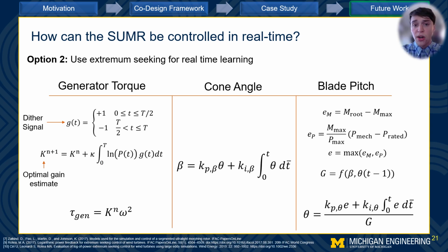While the control architecture shown on the last slide was shown to work well in our conference publication, this strategy lacked robustness to model mismatch and degradation in the aerodynamic properties of the blades, as our coning angle and tip speed ratio are tracked based on set points identified offline. Furthermore, similar to other architectures in the literature, the architecture on the previous slide relies on direct measurement of wind speed, which can be challenging to measure.